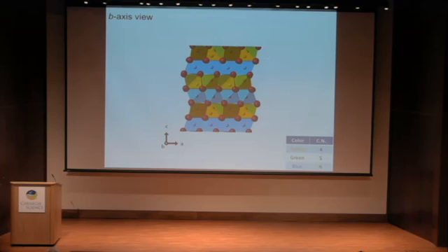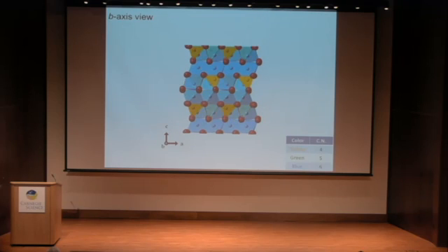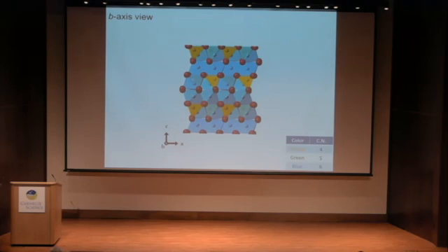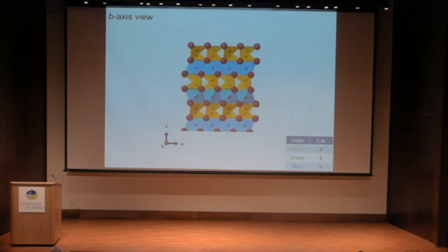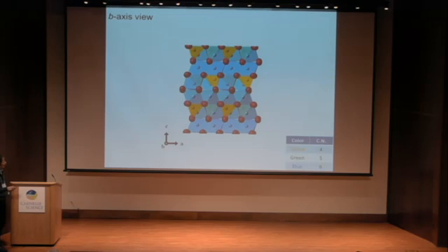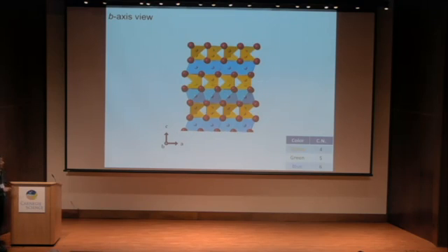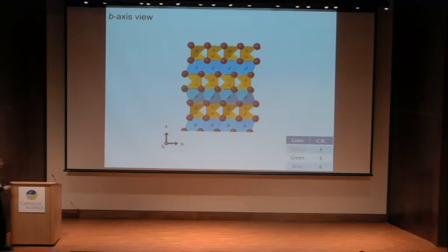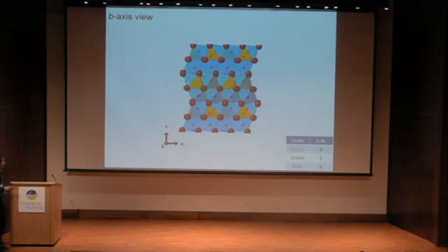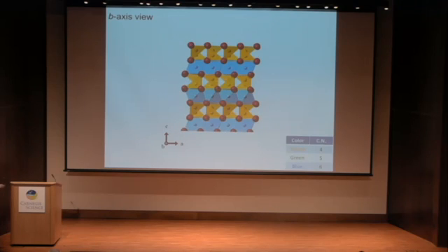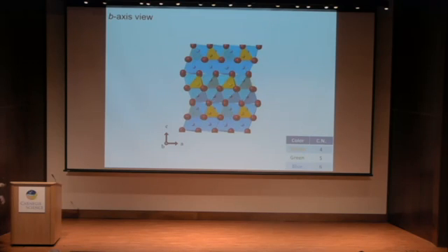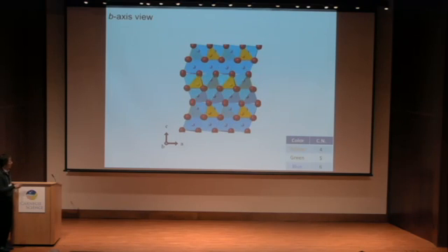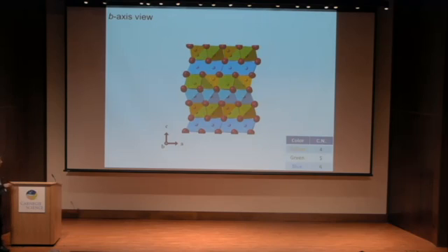The corundum layer and the spinel layer are the same, but in this direction, the close-packed layers of oxygen are shifting relative to each other. So this is kind of shearing. This kind of shearing may induce the recombination of tetrahedra to octahedra, or octahedra to tetrahedra.